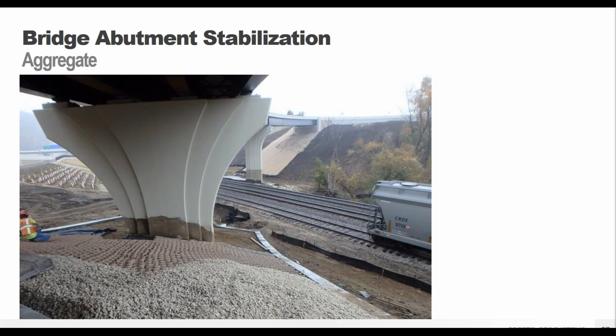Like I said, they also used it along railroad tracks and along railroad crossings. And like I said, the nice flexible nature allows it to go around those abutments when they are kind of unique shapes like they are here. What it's going to do is help prevent that water flow from tearing all of the soil or the stone around those abutments, because it's just going to flow over the top of the GEOWEB system. This way you don't have washout of your stone or your soil onto those railroad tracks, so you don't have any interruption in service. Always a good thing.